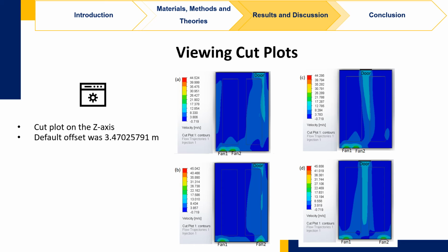The speed of air entering through the door decreased in scenarios A and B. When the door was placed facing a vegetable bed, it is clear that the area of high velocity in case D was greater than in the other cases, and the strongest airspeed is always at the fan, regardless of the position of the door and the fan.